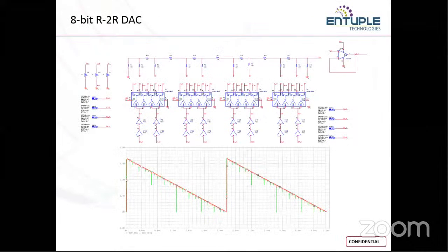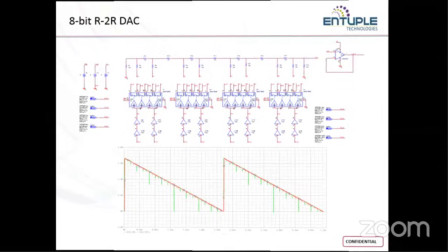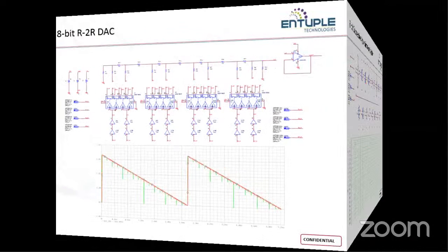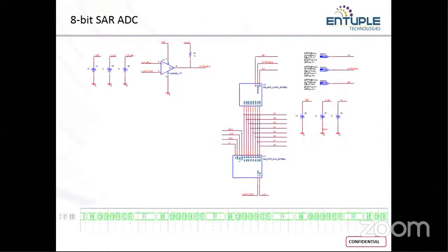This is how we designed using the ICs that were available in ORCAD: the successive approximation register, the sample and hold, the comparator, and the 8 bit ADC final block. Before you complete the overall connection, it is always better to cross check at each and every stage, so that you don't lose the plot, or you don't make it complex to identify where the mistakes happen. That is the reason why.